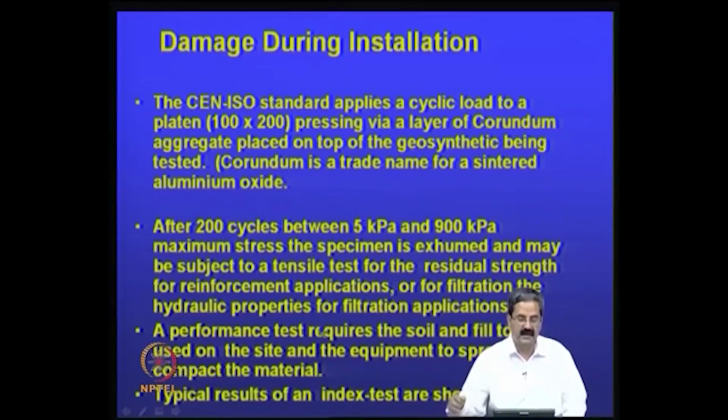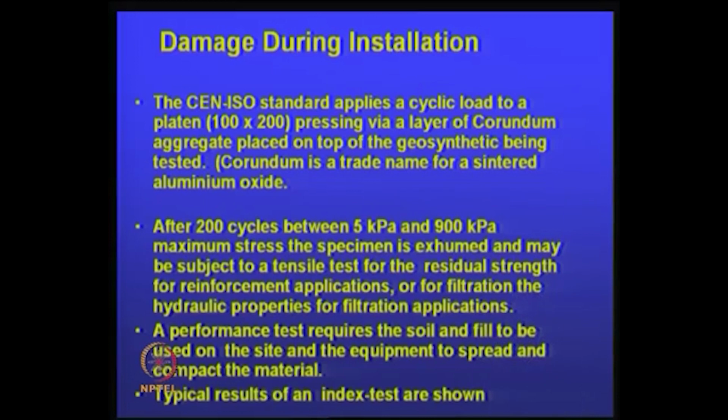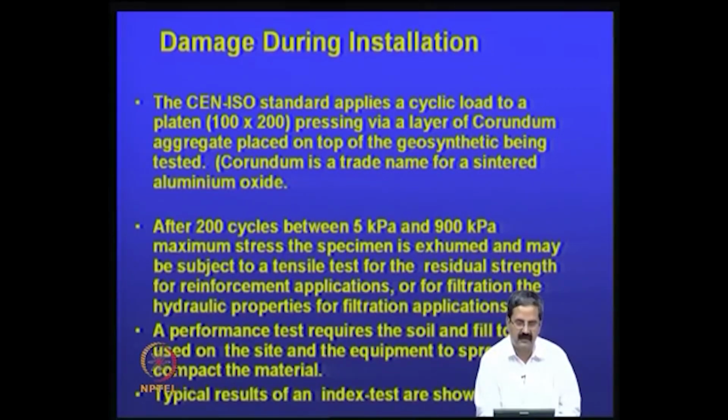As I said, damage should also be simulated, whatever the conditions are in the field. The geosynthetic product may be fine in the lab, and manufacturing conditions are all right, but when you use it for a specific application like drainage or filtration, it should perform very well. So, we have to simulate the damage of the particular product, and there is a method of doing it: after 200 cycles between 5 and 900 kPa, we remove the specimen and then tensile testing is done.